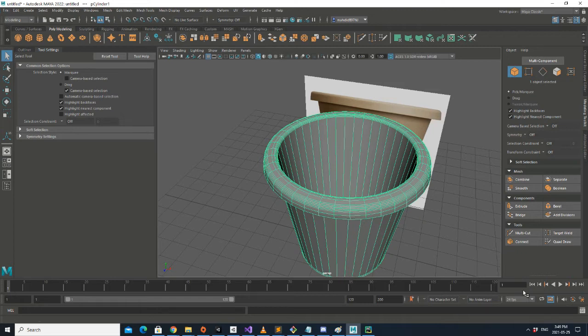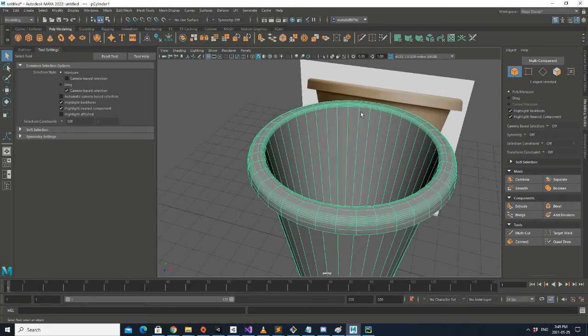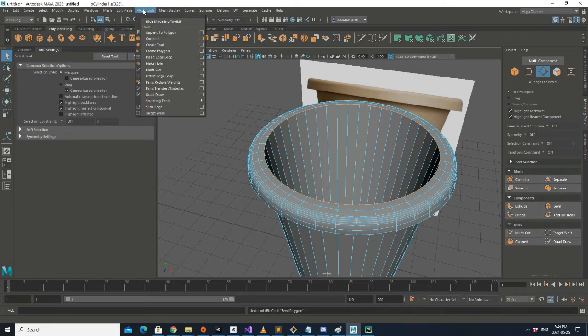Oh, one more thing. When you use the edge tool, sometimes when you click it, it's vertical, but sometimes it's horizontal. So how do you choose which one? I would say that's based on which edge you select. Let me just go back to the insert edge.